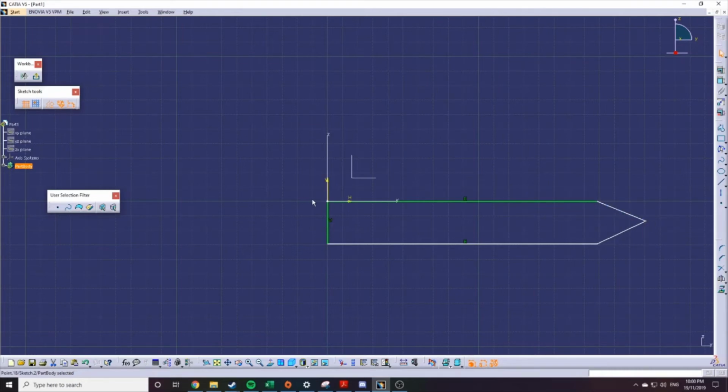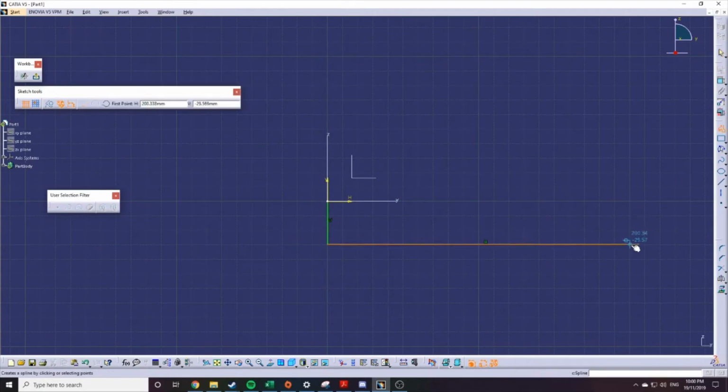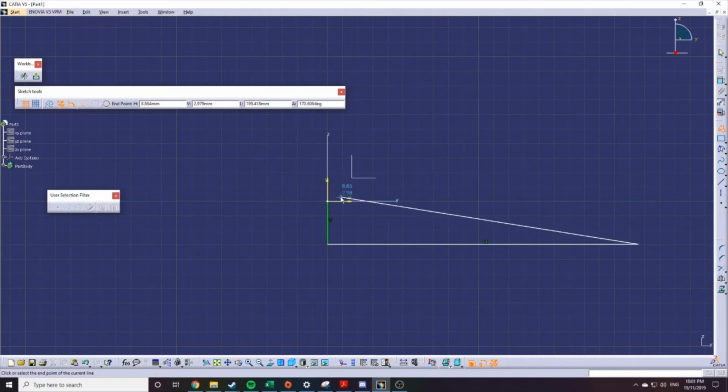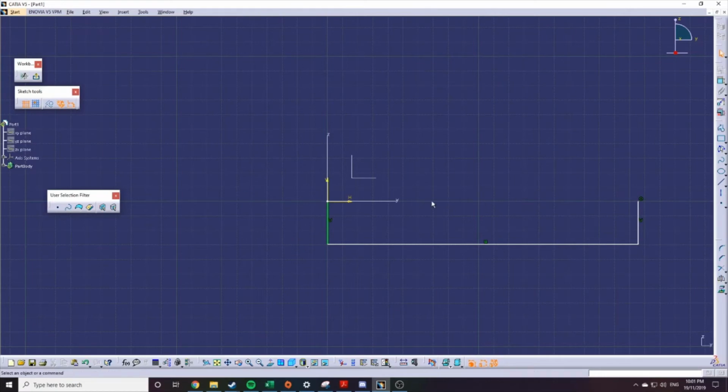When you're drawing, you would have seen before that a lot of this was snapping into place and using limits. So see, you can go here. You see the blue line that comes up. When you dot it, that will show that it's in line with the horizontal up there and the point up there, and it can move along. And then you'll see the blue point when it goes vertical. These blue points effectively just signify where a constraint will happen. You can turn this off, but usually it's pretty useful, so I just keep that on. It gets really messy when you're doing heaps of things in one sketch, but for the most part, you don't need to worry about that too much.